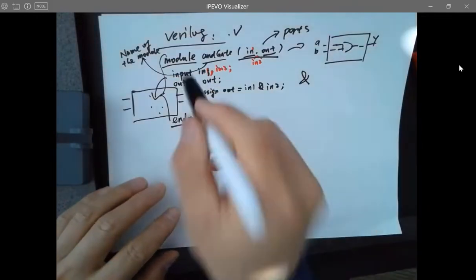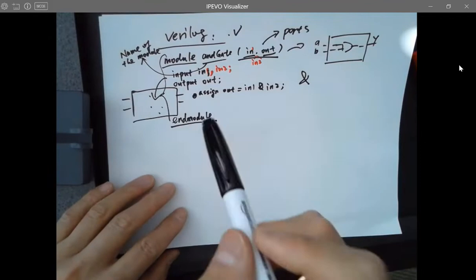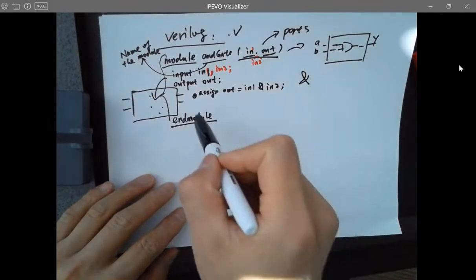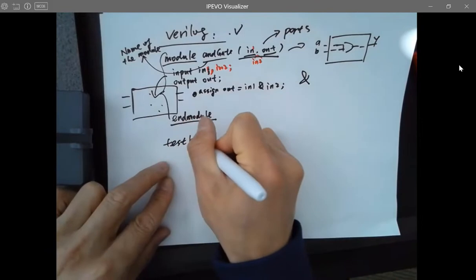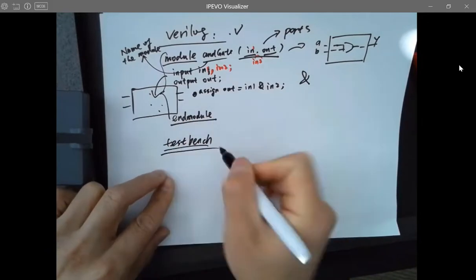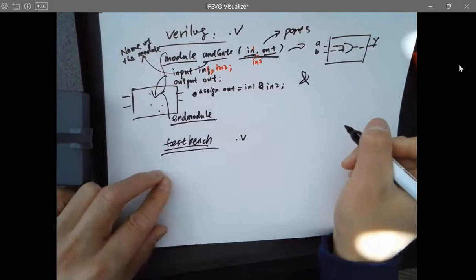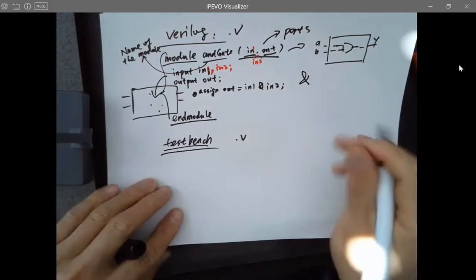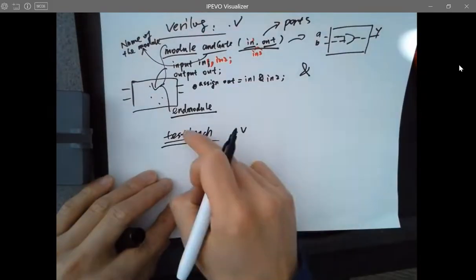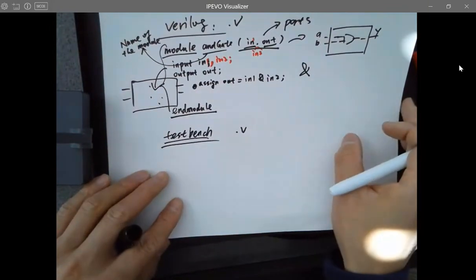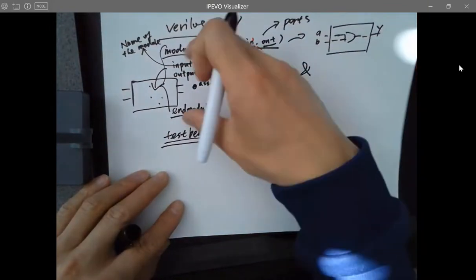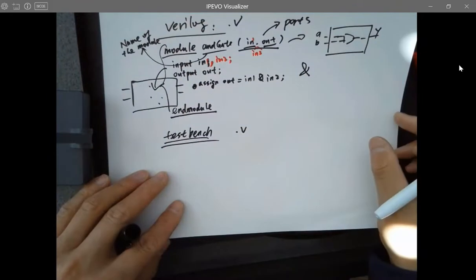Okay. There's no signal. When you're trying to simulate it, you need a test bench, which is also a .v file. You couldn't even tell the difference. It has a module and end module. So all the Verilog code is being included in between these two statements.